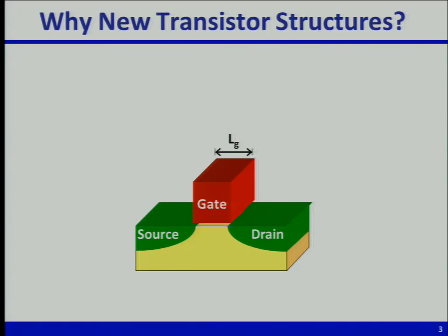Okay, so first of all, in the late 1990s, the industry was manufacturing CMOS chips with a minimum gate length. The generation of technology is quarter micron, so on the order of 250 nanometers was the gate length, LG here. And we knew that following Moore's law, within about 15 years, we would need to manufacture transistors with gate length 25 nanometers. In other words, we could project at a standard pace of scaling that eventually we would like to make transistors with gate lengths as short as 25 nanometers.